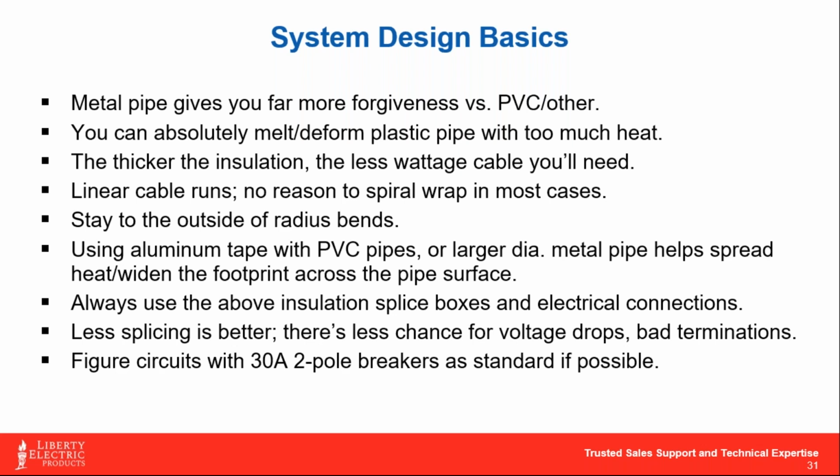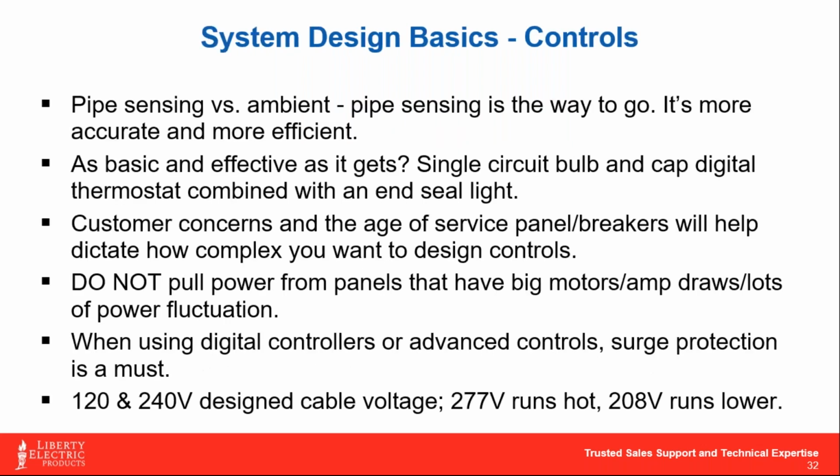So when we talk about sizing our circuits, 30 amp 2-pole is typically the way we go. But again, it's a function of the math. If you don't have 30 amp 2-pole breakers in the facility that you're designing for, then we have to work within the confines of a 20 amp or whatever we're given.